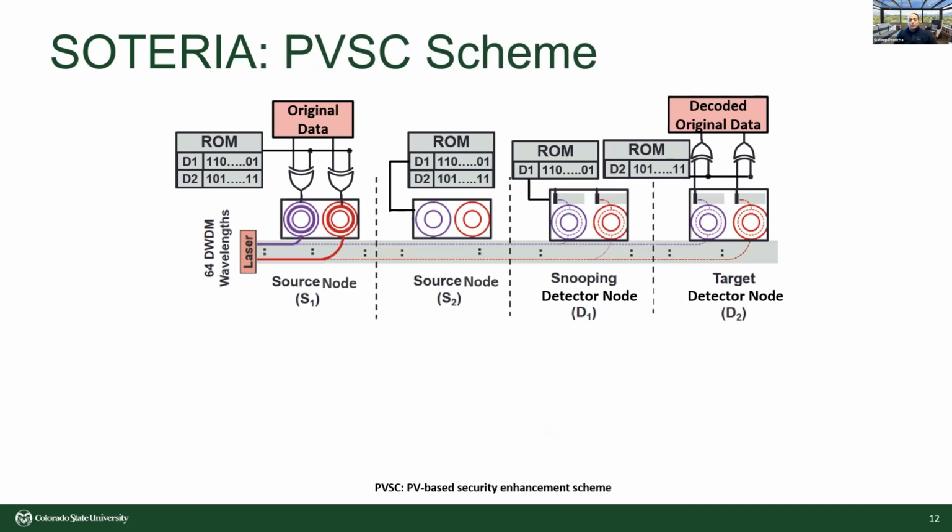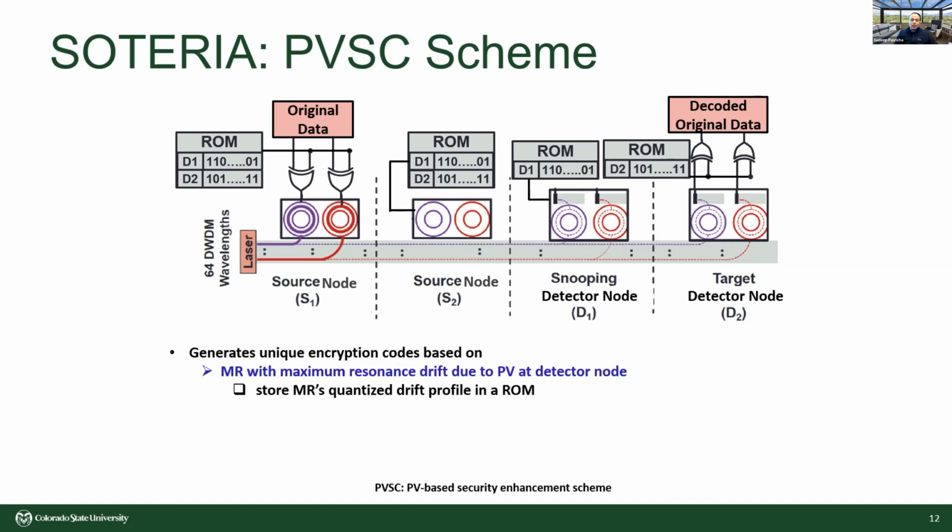At the circuit level, in order to ensure data confidentiality, perhaps the most classical thing you can do is to use some sort of encryption. But if you use conventional encryption techniques, they're quite heavy in terms of their overheads. So our goal was to design very lightweight, but yet quite strong and unique encryption techniques that are difficult to crack. And the way that we approached it is we looked at the domain of optical devices and their properties in order to help formulate our encryption protocol. We came up with an encryption technique that uses codes, where the codes are derived as a function of the drift of the microring resonator devices, which is a function in itself of the fabrication process variations on the chip.